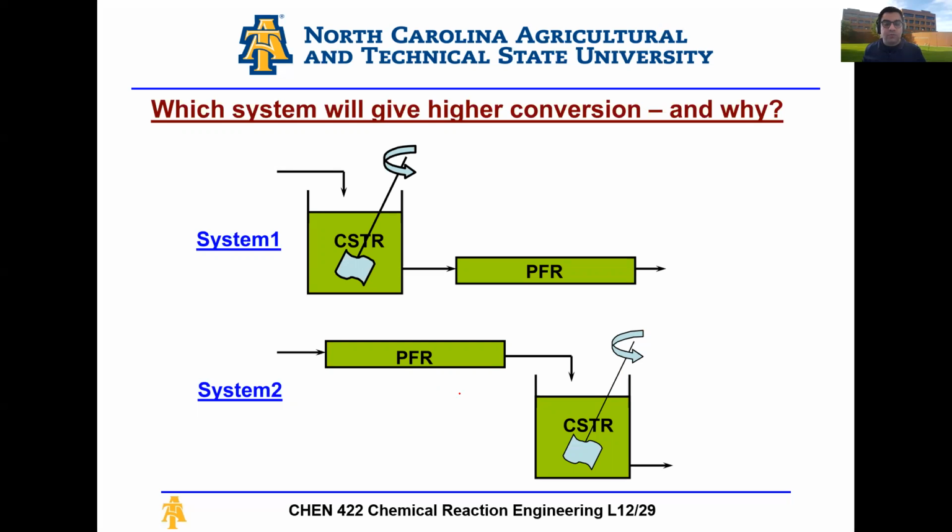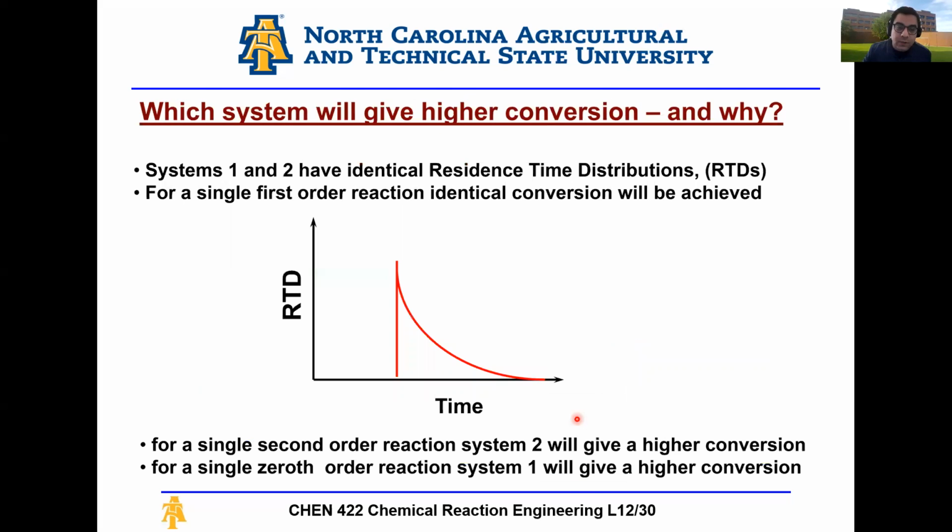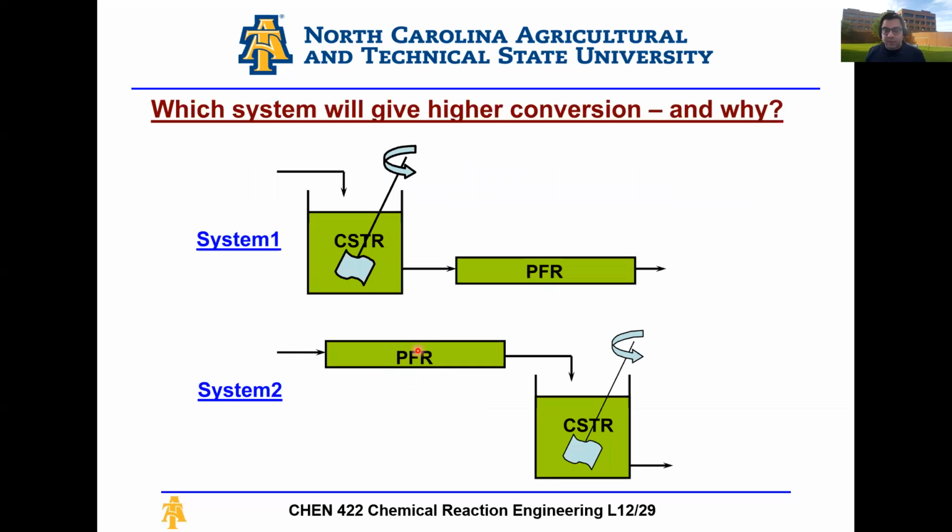performance? Intuitively at this stage, I expect you to say, well, it depends on the order of the reaction, right? And that's true. It will depend on the order of the reaction. It depends on the nature of the reaction, right? Maybe this configuration is better for a low order reaction. This configuration is better for a high order reaction. And if you have a look at the residence time distributions, you're going to find out that they are exactly the same. Okay, so this is another thing to think about when dealing with these systems.